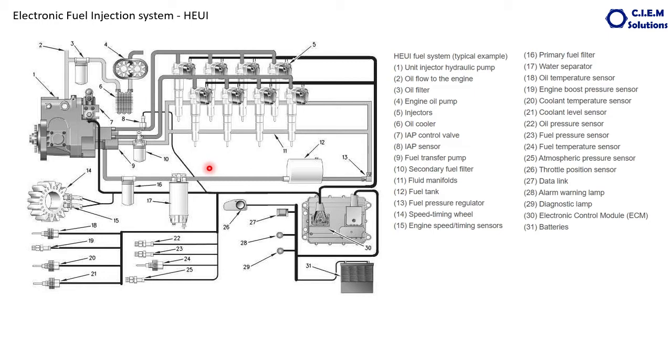Okay, oil levels. Then the coolant temperature sensor. The engine temperature should be at the desired, recommended level, approximately 95 degrees Celsius. It should not be more, and it should not be less than 80 degrees. So it regulates the fuel quantity accordingly. Next, the coolant level sensor. Then one more sensor. What we normally do in cars is press the accelerator by mechanical means. Here it is called the throttle sensor. So acceleration also is done through an electronic sensor.